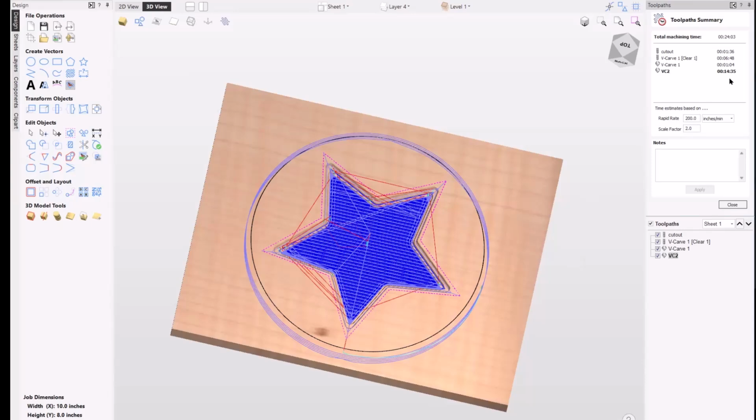Another good question. It depends on the setup, but yes, generally. Sometimes you do a roughing pocket tool path and you do a finishing tool path. Roughing, I often will go across the grain, but on the finishing, I always like to go with the grain because if there are any router marks or scratches, it hides them with the grain and it's a lot easier to scrape or sand them out. Cross grain router marks, as we know, are hard to sand out or scrape out. So yeah, I will usually orient it with the grain.